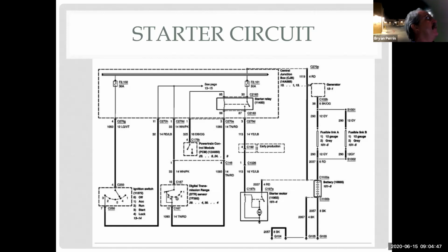Beats the heck out of what? Going underneath the car to look at the transmission, take apart the steering column to look at an ignition switch. How about check the relay? And many systems that use relays are like this, where that's the best place to start diagnosing it.